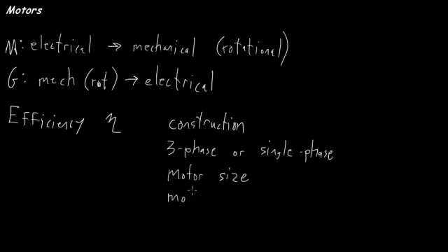We have motor load. For most motors, when they're running at full load or full power output, they are at their most efficient. As you decrease the load, so the motor isn't working as hard, the efficiency drops.